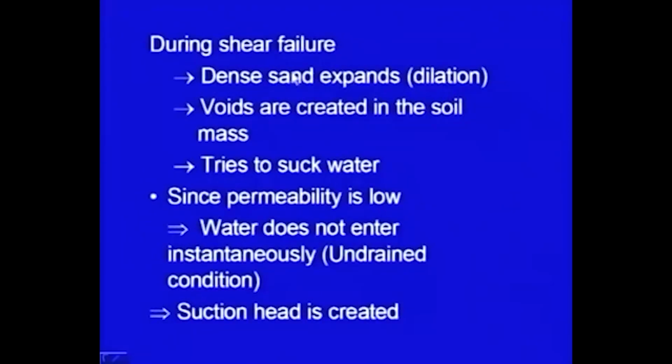If you remember your fundamentals from the soil mechanics course, if it is a dense sand, at the time of failure it should dilate. If it is a loose sand, then it should contract. So, if it is dense sand, it dilates, its volume increases, it expands. When it expands, voids are created in the soil mass, because the soil grains change their position, they roll over each other, they slide over each other, and voids are generated. So, voids are created in the soil mass.